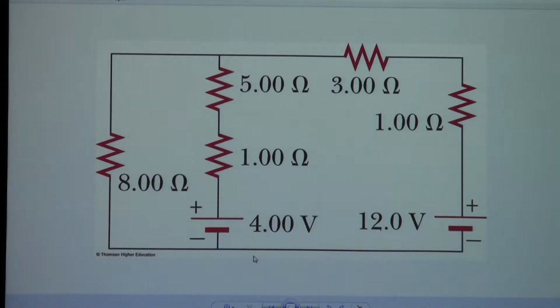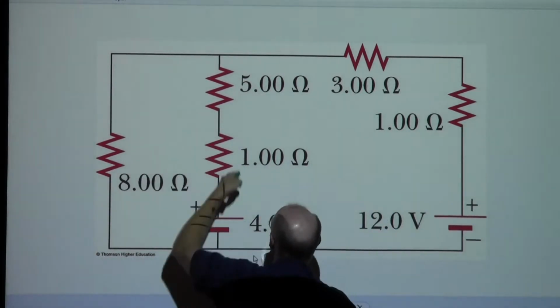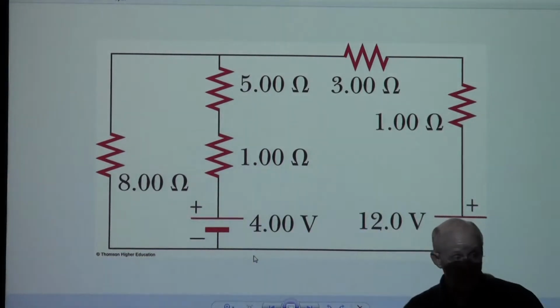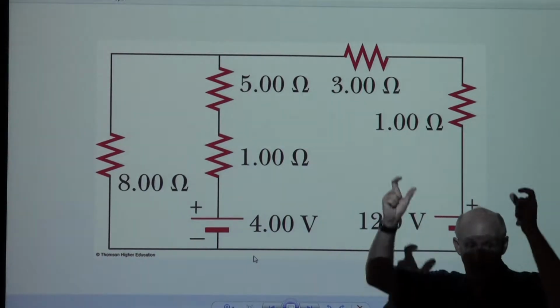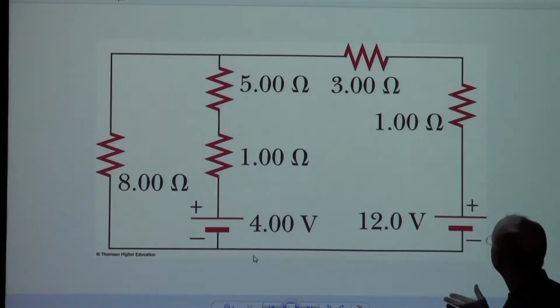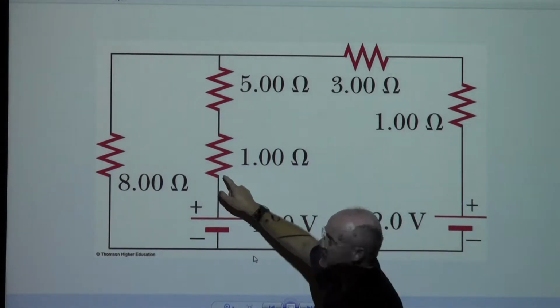They have an effect in the sense that the voltage would be different on one side of the battery or the other, which would clearly change our circuit and make it very likely that it is not series or parallel. When you separate it into 2 branches like this, you can quickly see that this branch and this branch are not in series. They separate off and look like they're parallel. In terms of the whole branch, yes, they are in parallel, but I would in no way say that that resistor is parallel to this resistor.